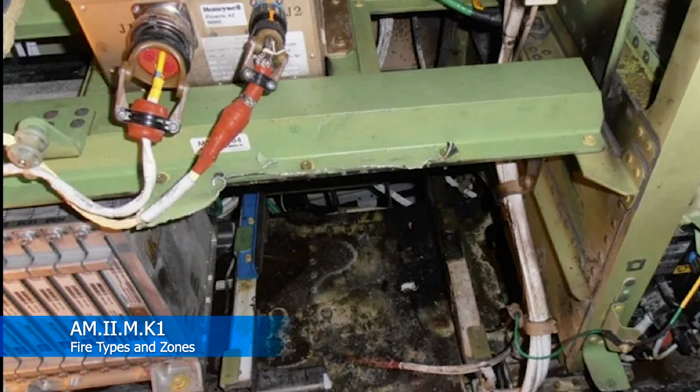Well, whenever you do that, when you reduce the surface area of one of those leads, it's almost like you've installed a lighter gauge wire. Well, what happens with lighter gauge wires? The electricity still has to pass through there, so the amperage comes up. Whenever the amperage comes up, in those little spots where it's barely touching, it gets really, really hot. You just think about the electrons making all that friction as it comes through there.